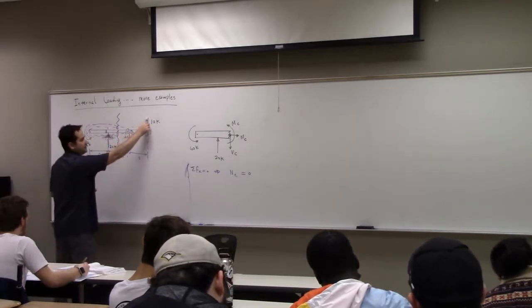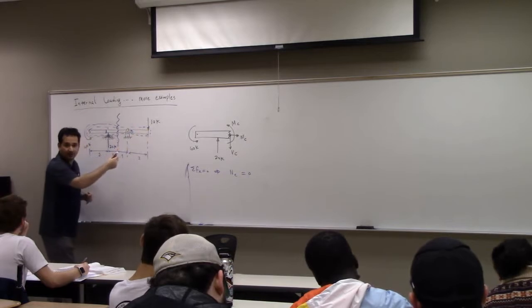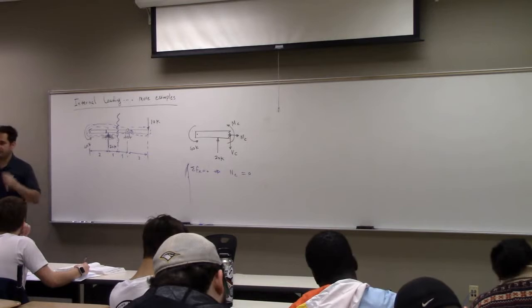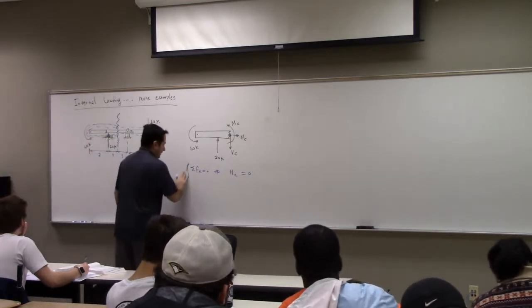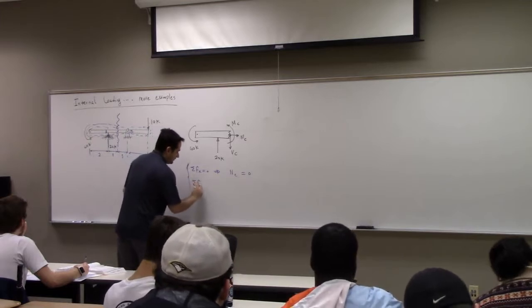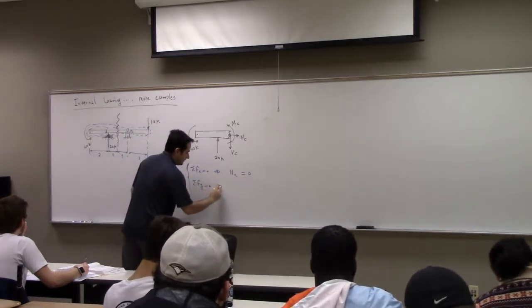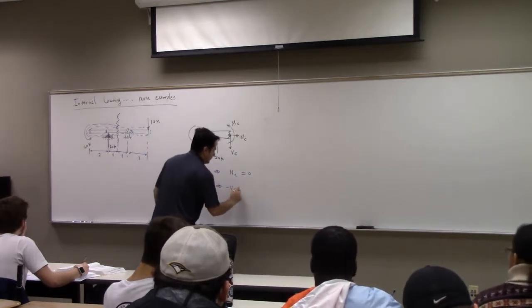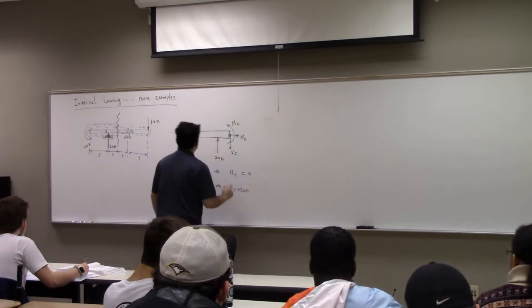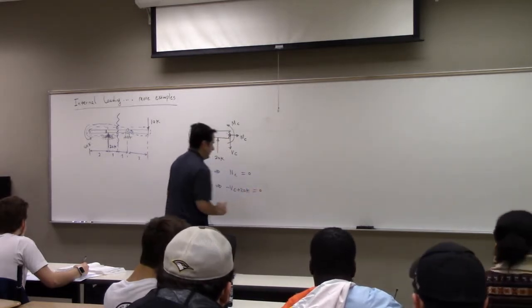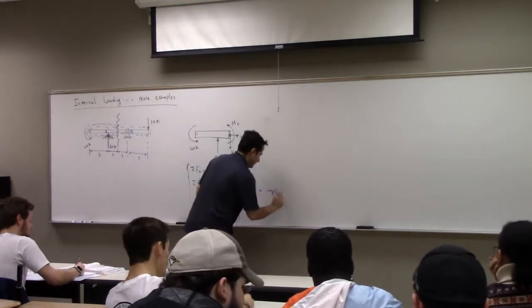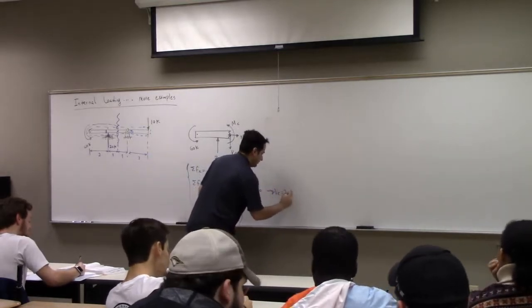Sometimes you have either an angled force like that, or some sort of other structure hooked up to this structure that causes internal loading, right? Axial loading, sorry, axial loading. Now you go to the next equation, summation of force in Y equals 0. So you get negative VC plus 20K is equal to 0. So your shear load, VC, is equal to 20 kilonewton.